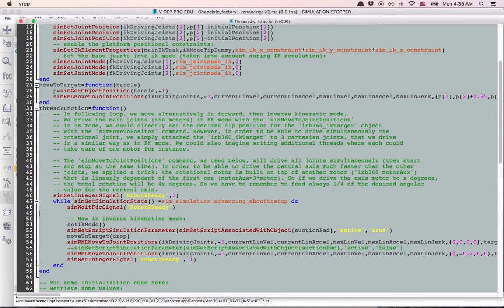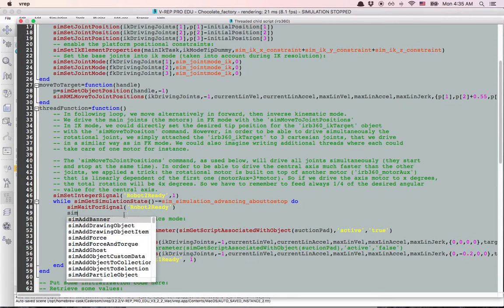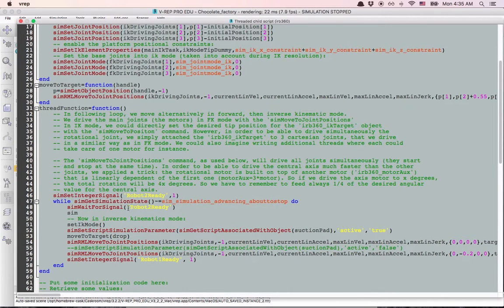And after this finally happens, after robot 2 sets the signal, what we need to do is immediately clear it. If we don't clear the signal, the signal will stay on and this will continue the loop forever. But we want to execute it only once per time. We want to wait for robot 2 to be ready every time we're executing the cycle.